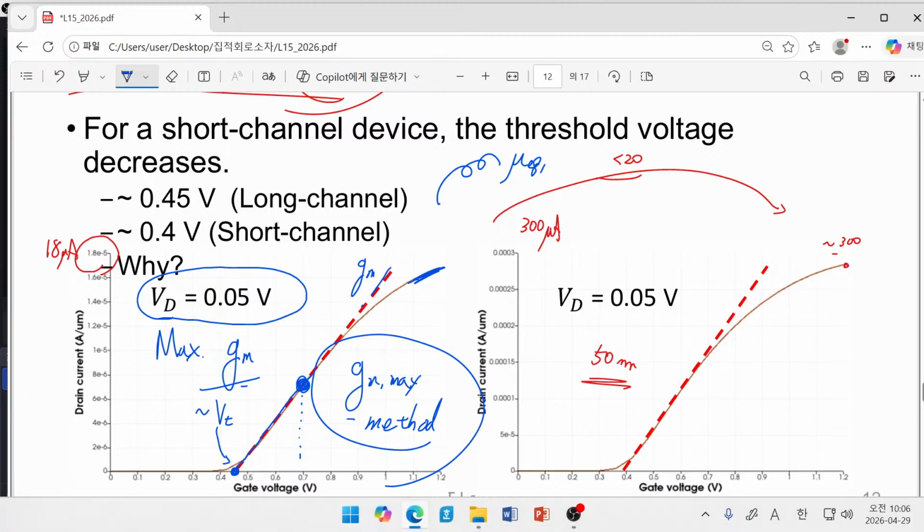Maybe you can ask me this question. Well, we have studied so rigorously about the definition of threshold voltage. Threshold voltage is given by flat band voltage and 2 times phi_B plus some more terms. Then why do we have to calculate threshold voltage in this way? Although we have a very beautiful idea about the definition of threshold voltage, it is not that easy to measure it.